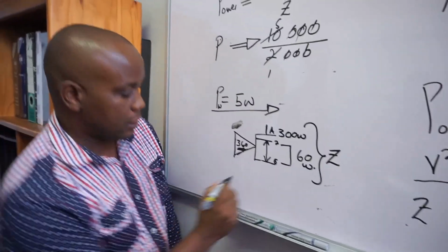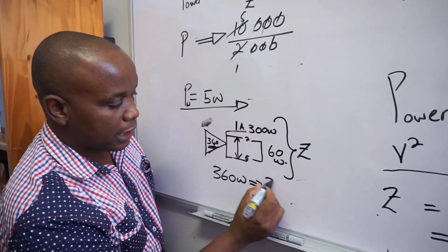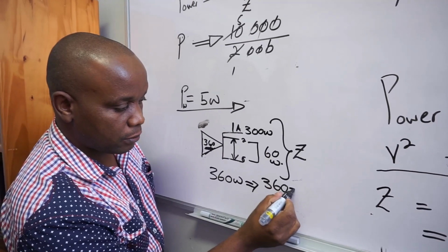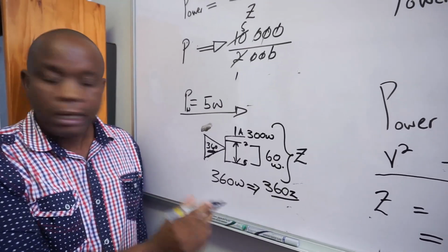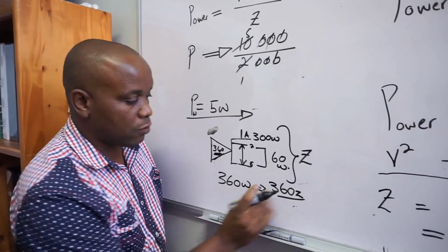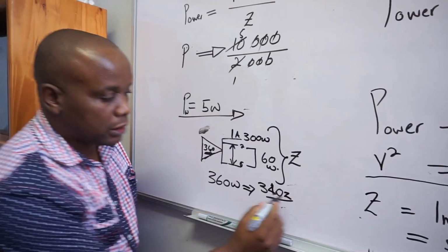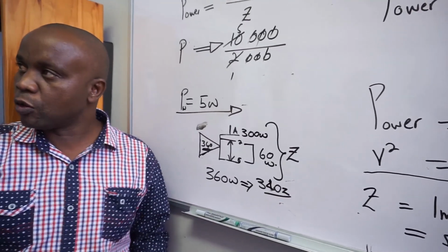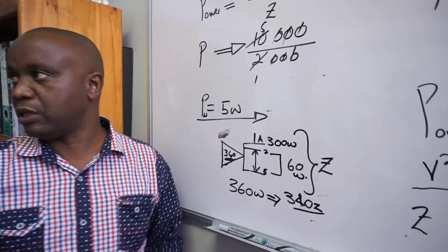I would advise a 360 watt amplifier, for example, to power a 360 watt zone. Yes, it can be done because it's within the same space, 1:1, but I would ideally have a 360 watt amplifier power a maximum of 440 watts. This then gives the amplifier breathing room. When you crank up the volume to maximum, you're not overdriving the amplifier.